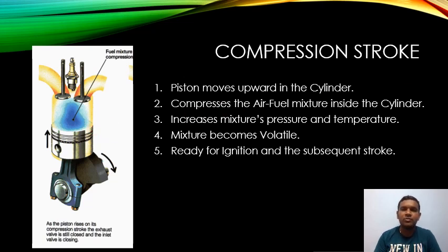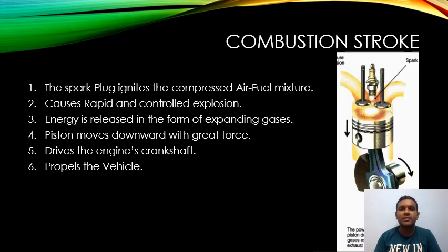The subsequent stroke here is the combustion stroke. The spark plug ignites the compressed air-fuel mixture. The spark plug, which is present above the cylinder, ignites the compressed air-fuel mixture inside the cylinder. Here both valves are closed. This is to be noted.